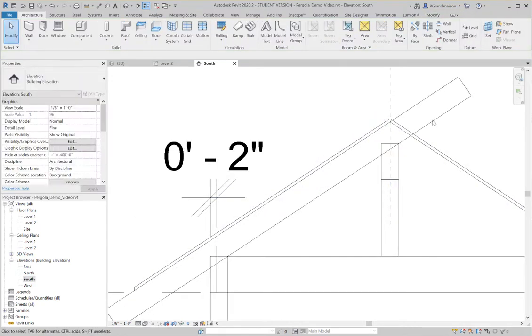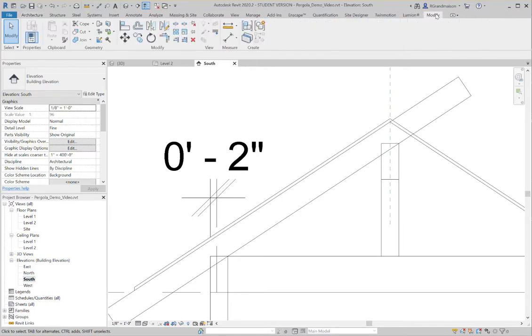I'm going to use this to trim all of these rafters here. So to do this, I'm going to go to my Modify tab, and then on the Geometry panel, the Cut tool. Read your command line or your status bar, and it'll say pick element to be cut. So I'm going to pick this element here, which is probably the frontmost rafter in my elevation view. Okay. Before I do that though, notice up on the option bar there is a multiple cut option. So don't click too quickly when you're picking commands and options. Read your option bar. Make certain you know what it's asking you, or the options that you have to work with.